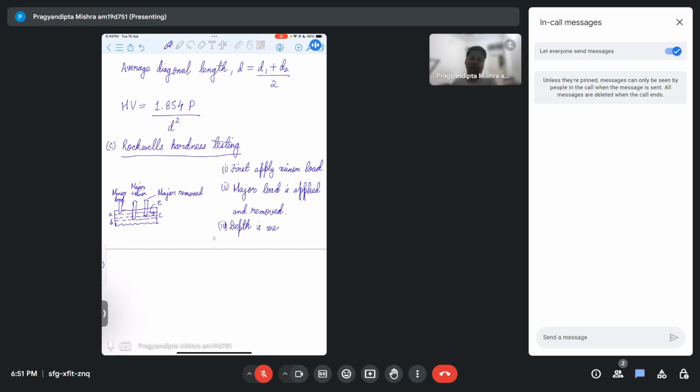Now, all types of testing measurements or all types of strengths that we have checked till now were based on the fact that we are applying load in a controlled, structured way, right? What if the load is suddenly applied? What happens in that scenario? At a very high strain rate, we are applying load. Then the material behavior will not be the same as what we see for the simple case where strain rate is smaller, or where strain rate is applied in a very controlled way. So material will behave in a different way when impact load is applied. And this is something that you would have observed in many places, right?